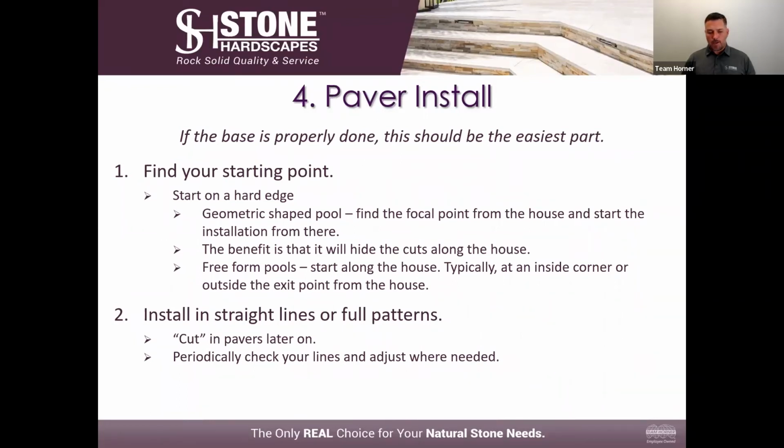And then periodically check your lines. If you just start laying the pavers down and take off and not pay attention, a little gap here will be a massive gap 10 feet away. So you're constantly wanting to check your lines.